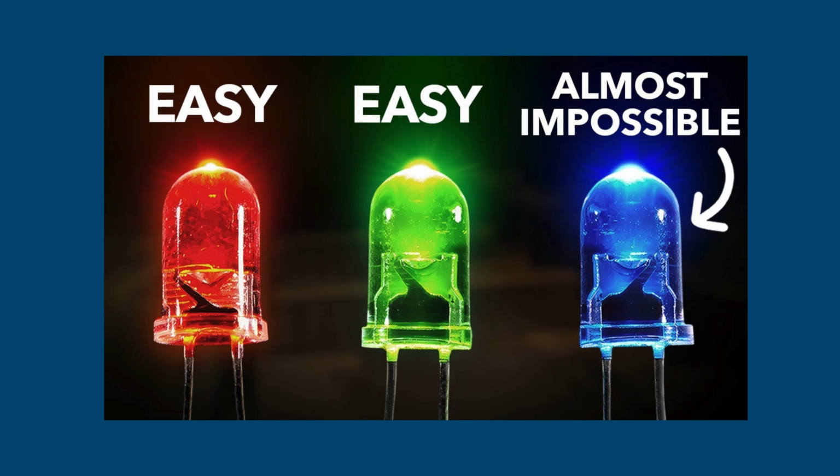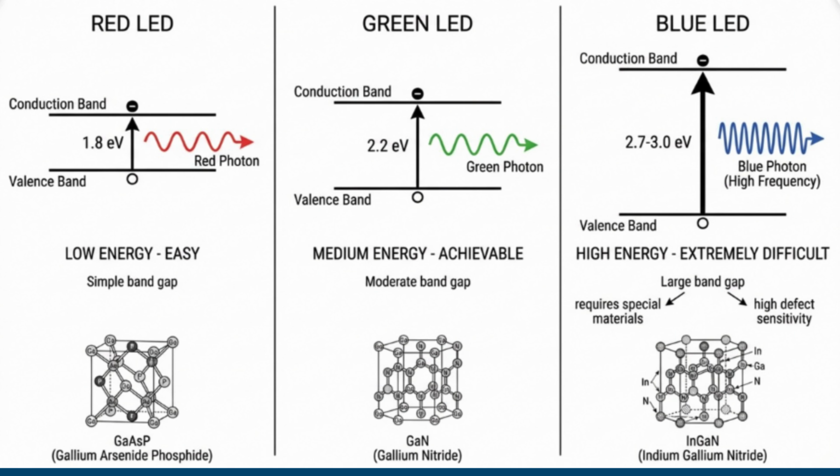Blue OLEDs remain the most challenging due to high photon energy leading to photochemical instability, limited availability of high triplet energy host materials, and efficiency-stability trade-offs. Current commercial devices often use hybrid architectures combining phosphorescent red and green emitters with fluorescent or TADF-based blue emitters.